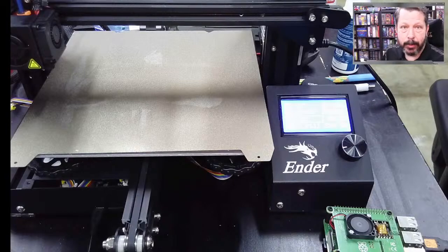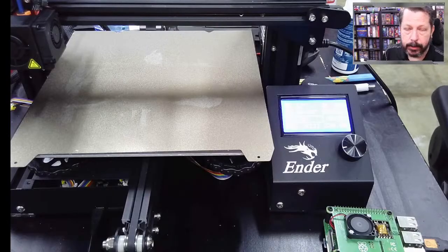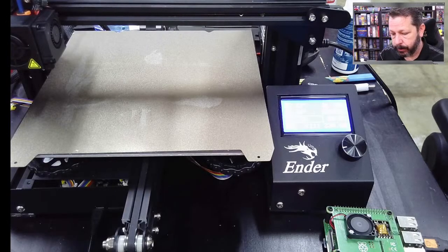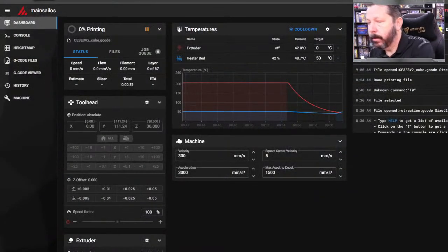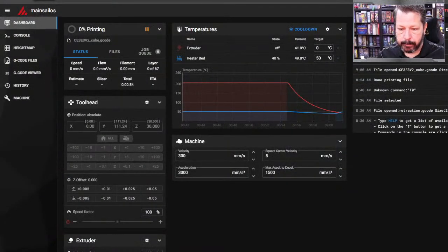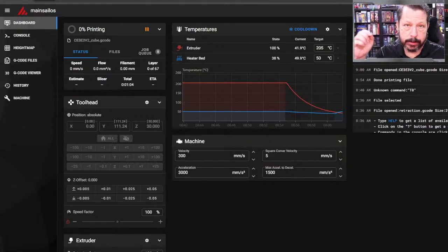They need to be 0.4 millimeters, but if there's some other number, maybe it's over or under extruding, we can go back to Cura, and in our flow rate, we can up our flow if we're under extruding, you know, our walls aren't quite as thick as they need to be, or we can lower our flow if we think the walls are too thick.